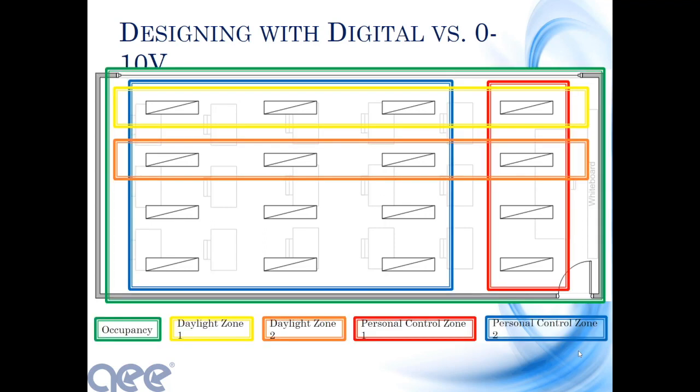There's a lot there if I look at it from a zoning standpoint. I want a zone for the whiteboard. Ideally in this room, I could have the lights dimmed over that screen as opposed to the same light level as the rest of the room. But I do want common control over the classroom itself. That way I can have in front of the whiteboard maybe 5% and then 70% elsewhere, so people can take notes but don't fall asleep.